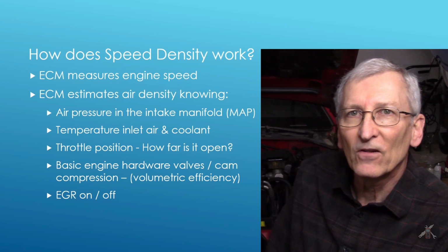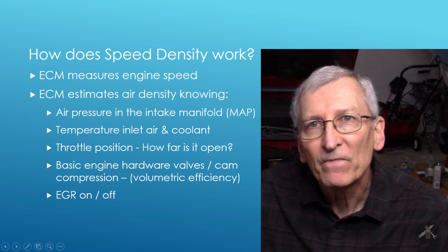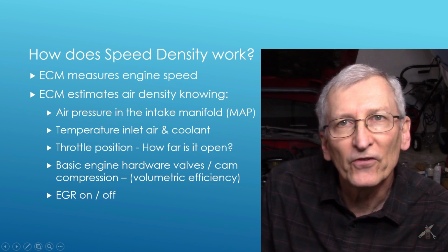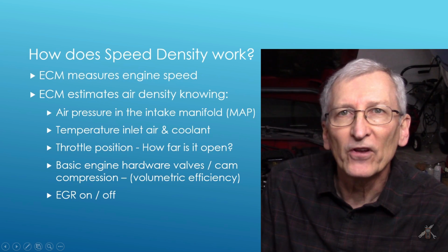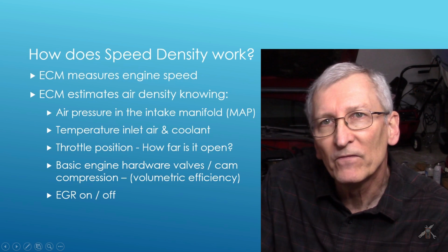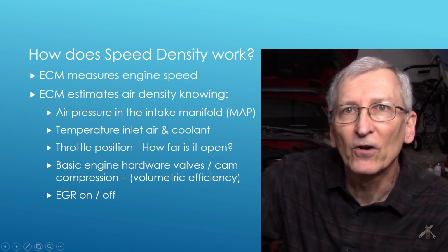Now, in a car like mine with a mass airflow sensor, if I go change the cylinder heads and put different valves on it, or I change the cam, the mass airflow sensor picks that up right away and says, hey, airflow changed.